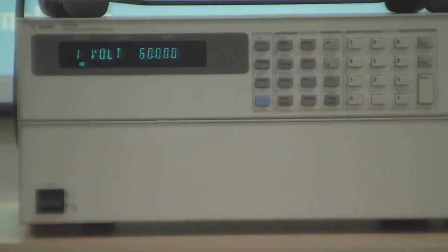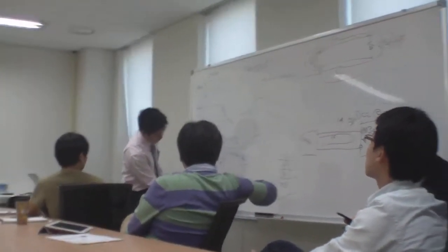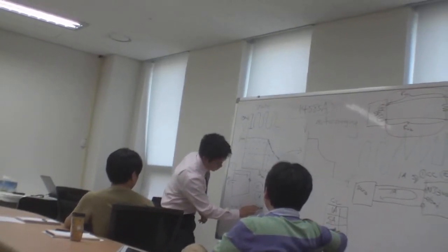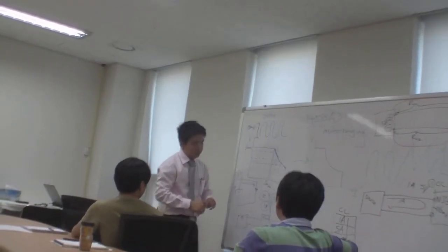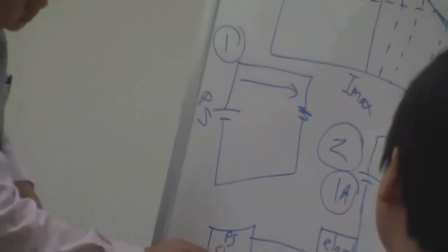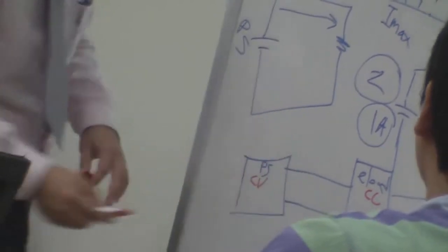So most likely, what happens is usually this. If you have a power supply, let's say this is your power supply, you connect it to the E-load. Whatever the setting is here cannot be the same setting as here. For example, if this is a constant voltage power supply, the E-load has to be constant current.